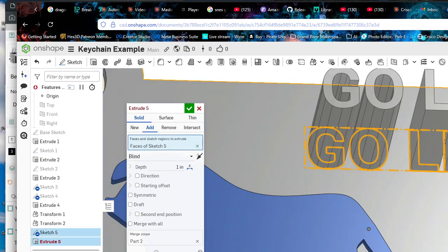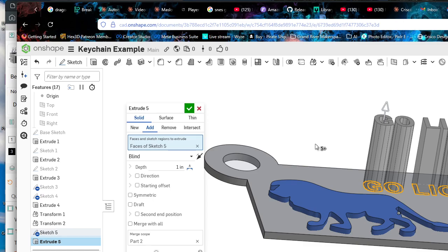So my drawing is not fully defined. Let's see what we got. So your spline drawing like that will never be defined. So what do I need to do to get that so I can start manipulating that? You just hit the checkbox as long as it is an enclosed object. The splines, freeform, that kind of stuff will never be fully defined. Then when I extrude it, that lightish gray will go away? 100%. And the image should disappear.